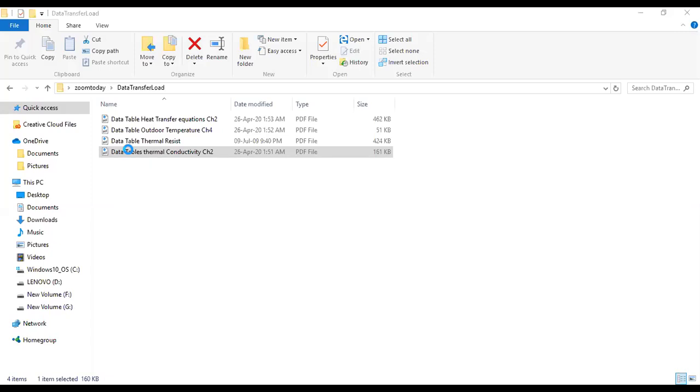Using Newton's law of cooling, Q is equal to Hc, the convective heat transfer coefficient, multiplied by area, multiplied by the temperature difference between the heat transfer surface and the free flowing film of fluid over it. The fluid may be liquid, or it may be gas. So for convective heat transfer, use these Hc values: forced convection, free convection of water and air. It depends on whether water is boiling or not boiling. So you will need heat transfer calculation.